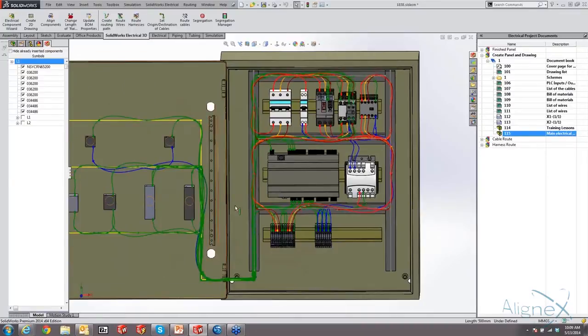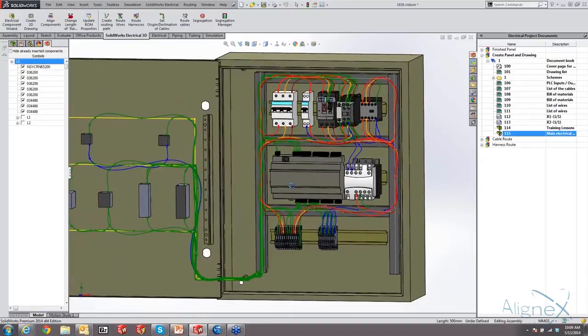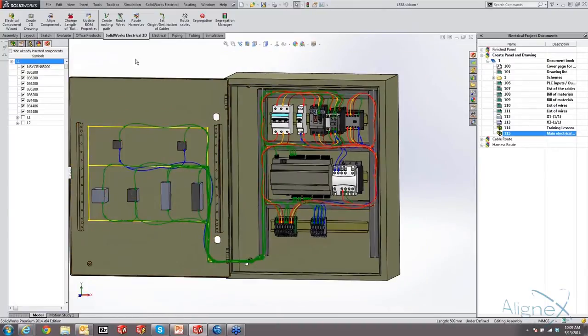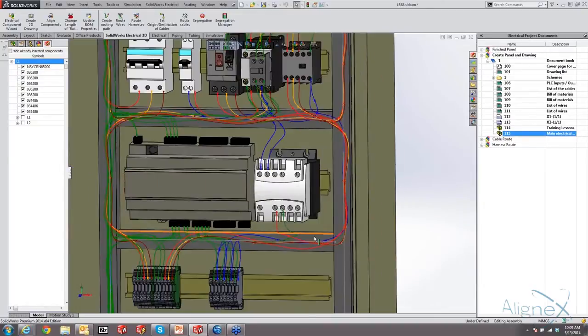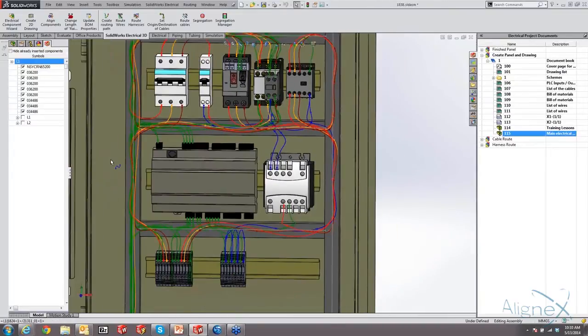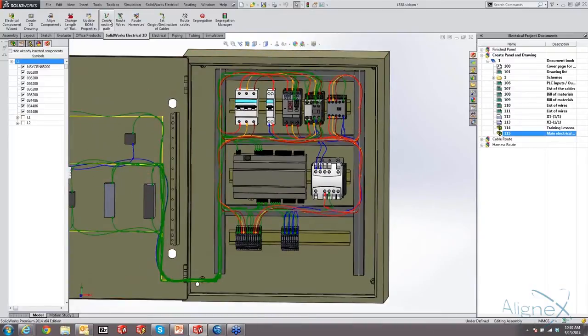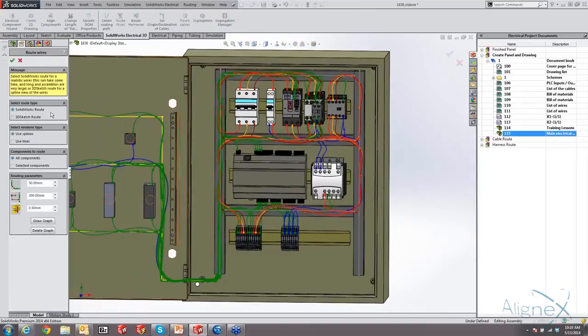Okay, so there is now our 3D wires, and that's what it looks like going through our wire trays and over to the door and connecting to our components. And you can see, based on our segregation, we told that 24-volt AC wire to stay out of here, so it now doesn't go through there. It actually routes over to the other side automatically. Okay? All right, so now we have that. Let's go ahead and make this our 3D wire. So I'm going to use the SOLIDWORKS route this time and say go.